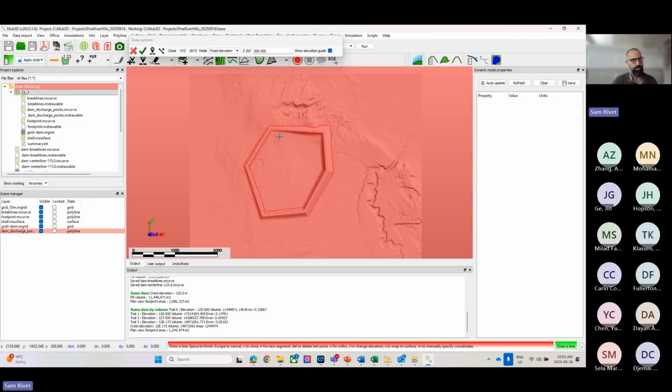And I'm going to draw a polygon at 200 meters in elevation. And we're going to take a look at some polyline draw tools here. Okay, so this is going to be my first cell, just defining the west area. Just digitize some points, and I want this to be closed, so at the end I hit C. I want to keep drawing lines. I don't want to stop adding line work to this layer. So hit N. And now I can continue to draw lines and add it to that layer, as opposed to maybe drawing multiple layers, merging them together or whatever.